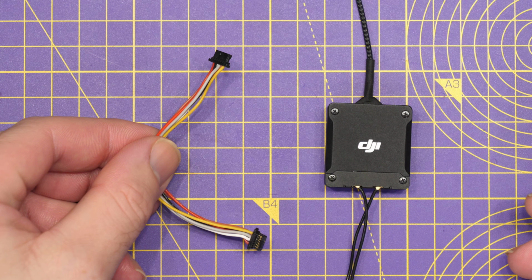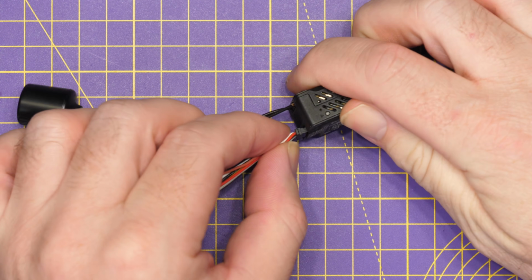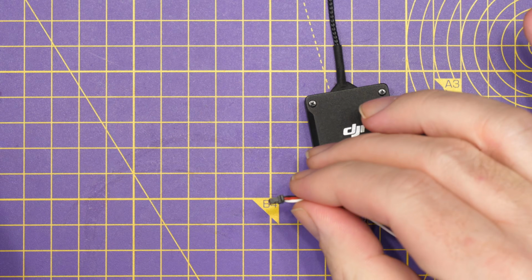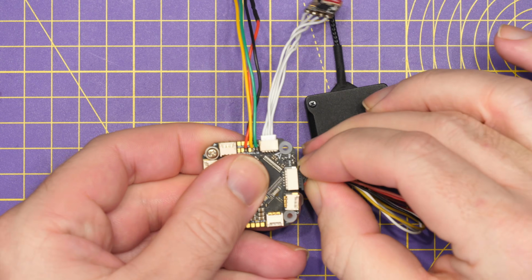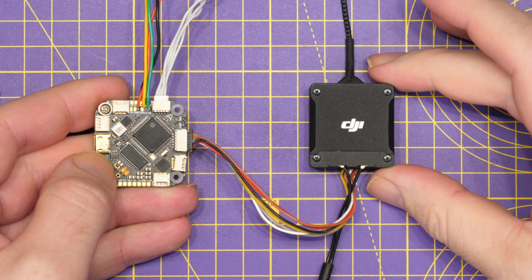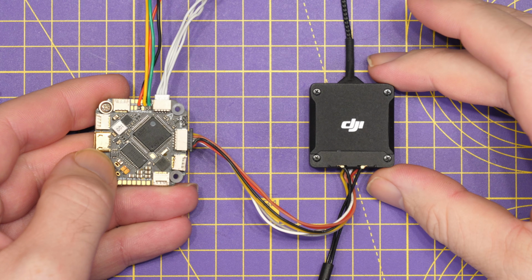Now, there is one last thing that you do need to take into account with regards to power on your O3 system that is critical. The O3E unit does come with a harness with a connection on each side. There are many flight controllers that have the exact same connector for their digital VTX input. However, do not assume the pinout or the wiring order is exactly the same. Just because DJI have used a connector that is the same as what manufacturers use on their flight controllers does not mean it's pinned out the same. It is possible that it could be pinned out differently, and plugging it in wrong will result in your O3E unit getting burnt out.